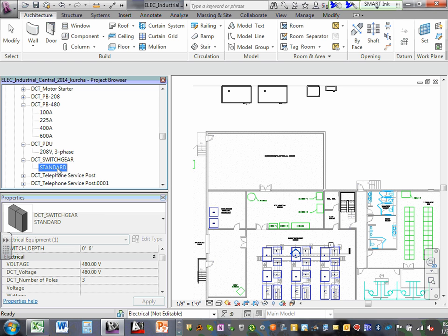We're going to have a switchgear, guys. You saw the big circuit breakers that we're going to have in parallel switchgear. The way they size them, they put no more than 4. If you saw Boston Scientific, we didn't have them, but we have something similar. They can put up to 4 circuit breakers, 1,000 amp each, into one cubicle, one section.